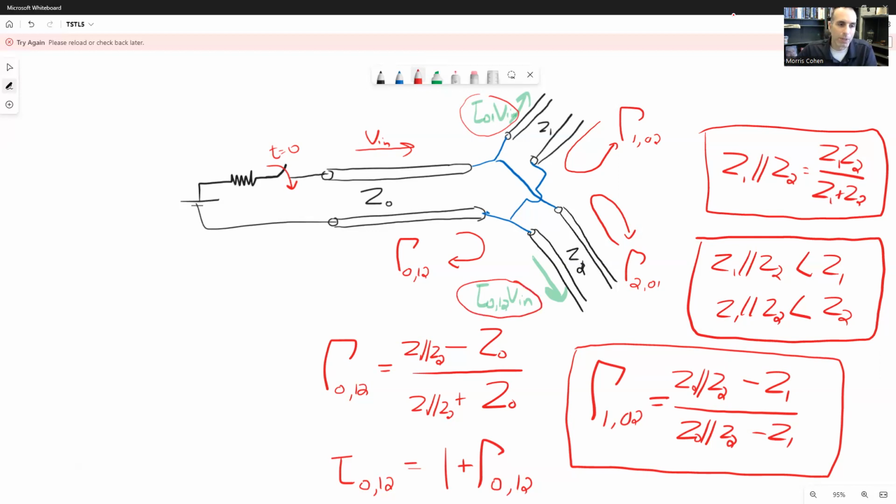That kind of makes sense, because if I have two resistors connected in parallel, I can guarantee you that their voltages are the same, but their currents are different, assuming R1 and R2 are different. We're going to have different currents flowing through R1 and R2 separately. So a parallel fan out guarantees the same voltage is going to appear on both lines, but it does not guarantee that it will be the same current.